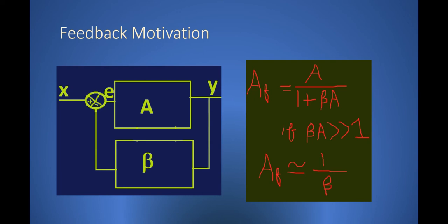So when you have feedback in your amplifier, the closed loop gain then depends only on the value of certain resistors which are frequency independent, and furthermore their values are more or less stable, and they are more accurately known than the value of the gain of the amplifier.